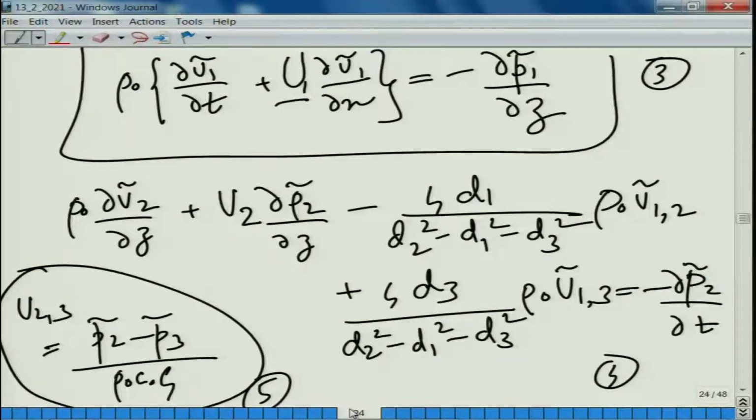It has been shown in previous papers, like one famous paper by Munjal and others published in about 87 in the Journal of Sound and Vibration, where they have also ignored the convective effects of mean flow because it makes life easy, it simplifies the algebra and a lot of terms drop out, they just evaluate to 0. So, we need not consider them, but they can still account for the most important dissipative effects of mean flow, which we are going to see now by using appropriate perforate impedance expressions.